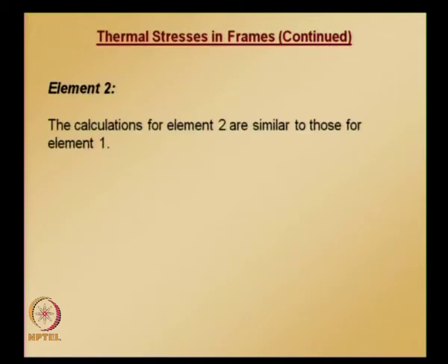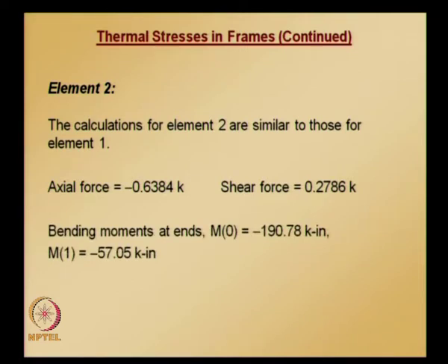Similar calculations we can also repeat for element 2. Calculations for element 2 are similar to those for element 1. So, the details are not given here explicitly, but the final axial force value, shear force value and bending moment value are given, and here also when you are calculating the element forces for element 2 for axial force and bending moment, we need to apply the fixed end corrections, whereas for shear force no such correction is required.